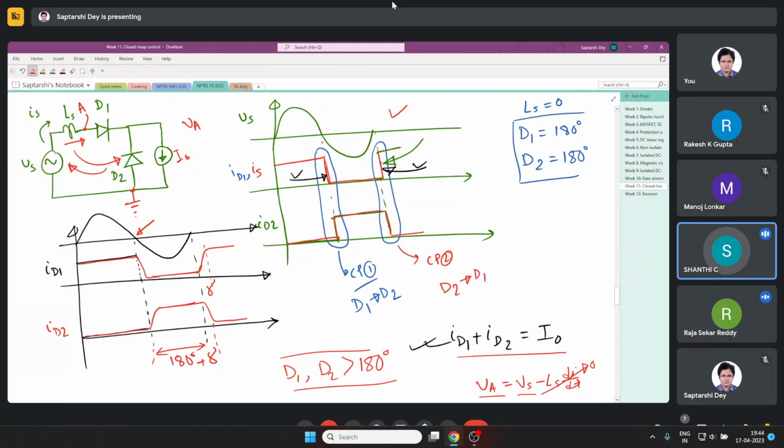Sir, then who is supplying energy to D2, sir? I naught. Current. Yeah, that's what I'm asking. Raja, you are saying something basically. Sir, just a minute, this I naught is I naught basically in this circuit. The current I naught is commutating between D1 and D2 based on the polarity of the voltage source. And the inductor is introducing a delay.